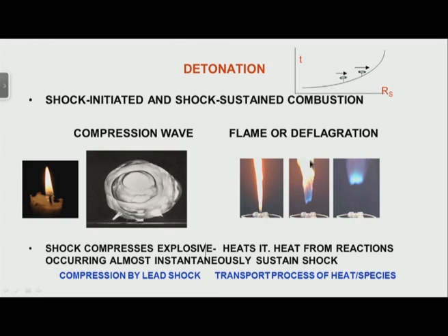Instead of having an expansion in a flame, I have something like a compression, a huge compressed type of gases being formed, and this shock compressed movement of the flame front is what is referred to as a detonation. In this case, you do not have transport of gases like what we had for a flame. What you have is a gas mixture in which you form a shock wave and the chemical reactions which drive the shock wave, which we call a detonation.